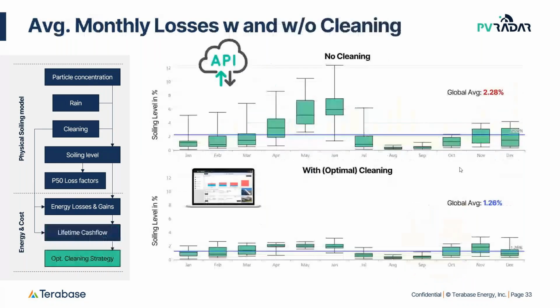Right. Okay. So this brings us back to the soiling loss factors, just to close the loop. The result of the first part of the presentation was what the API sends back, and that is the soiling level, assuming no cleaning, based on historic data of earlier years of production. That gives you, in this case, values in June, a median P50 value of 6%.